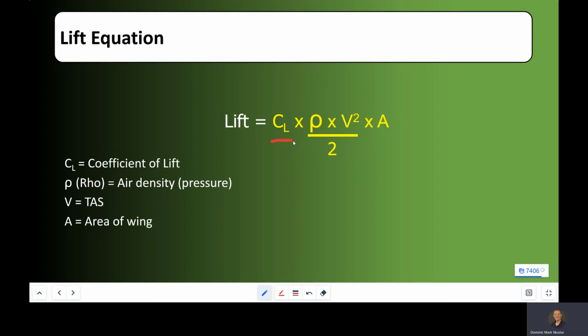They are developing that technology for later in the future, but for our purposes, the coefficient of lift, that's the shape of the wing, is constant. Our wing area, given the same configuration, flaps up, flaps down, does not change. So those are your constants in there.